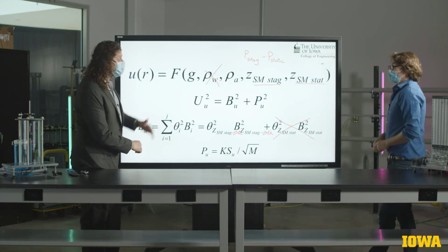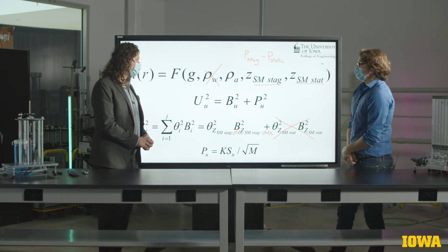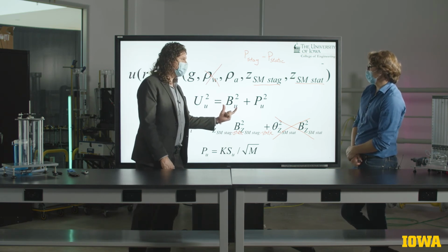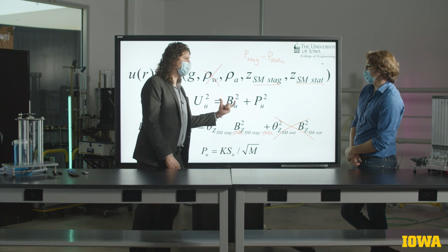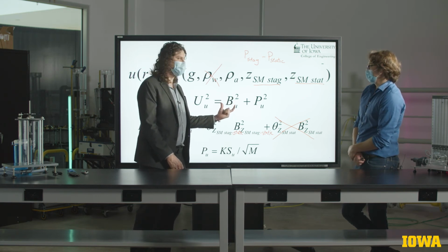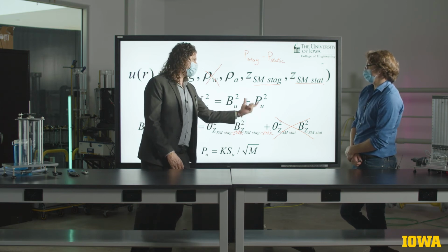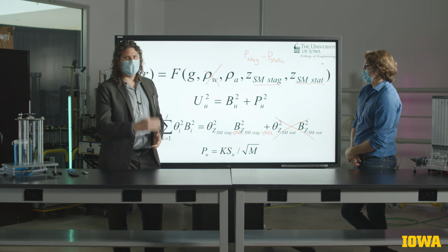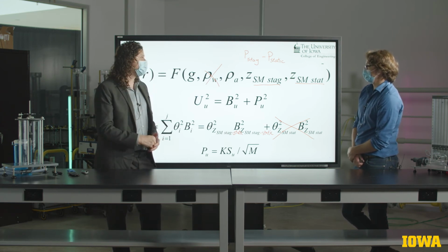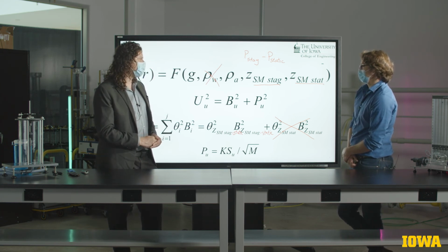Yep. But we still have two sources of uncertainty associated with this experiment. We have an uncertainty associated with our bias limit, because the instruments have a finite resolution, and an uncertainty associated with the precision limit, because our measurements, if you remember during the performance of the experiments, vary quite a bit during the experiment. So there is a random component in the measurement of those.